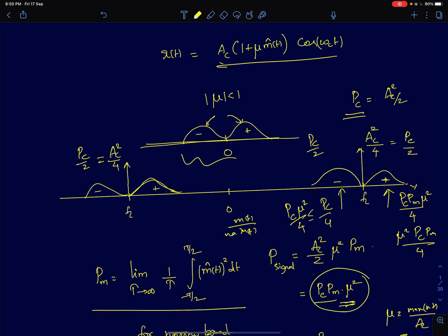So here we have a low frequency message signal. Again, it's a real message signal, so it will exhibit conjugate symmetry, meaning at any given frequency f and its equal and negative frequency, the Fourier transforms will form a conjugate pair. They will be conjugates of each other. In amplitude modulation, we simply multiply it with a carrier signal, so the same thing gets translated to the higher frequency fc as shown here.